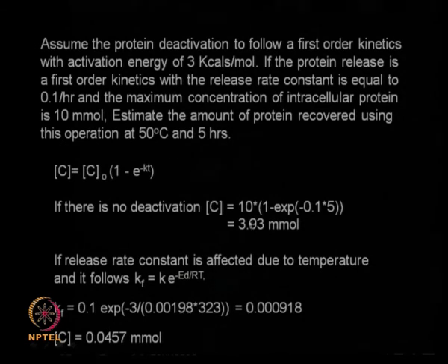So you see that temperature will play a very important role in the amount of product you are going to collect at the end of the process. That is why many of the mechanical agitators may have inline cooling, that means there might be a cooling facility inside the equipment itself, so that the temperature rise is practically minimal, maybe 1 or 2 degrees, not in terms of large values.